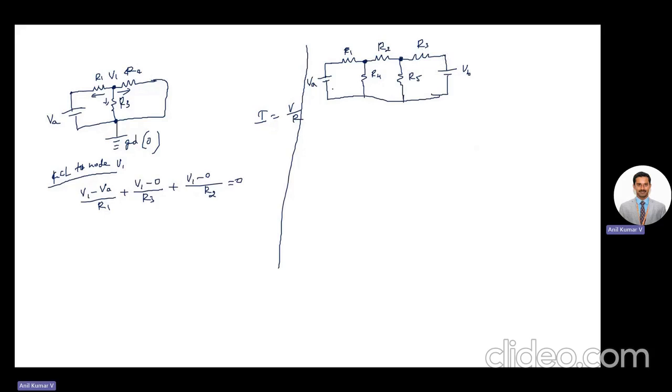And similarly, if you see the bottommost, so VA voltage source, R4, R5 and VB. So these things are just wires, right? So all are connected to the same junction and this will be one node. So in total, in this circuit, you have three nodes, right?